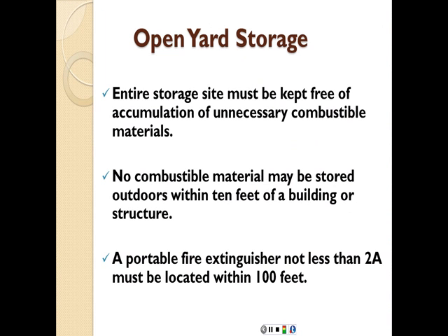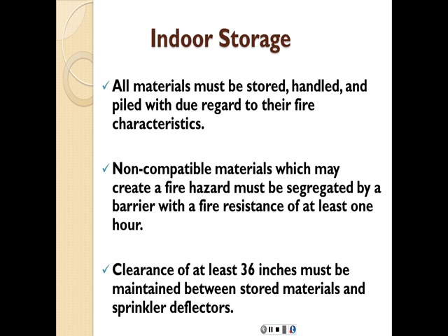Entire storage site must be kept free of accumulation of unnecessary combustible materials to try to limit the occurrence of fire as much as possible. No combustible material may be stored outdoors within 10 feet of a building or structure, because in case people are trying to get out of the building, they do not need to be exposed to an additional hazard of fire facing them. A portable fire extinguisher not less than 2A must be located within 100 feet. So that's in case of open yard storage.